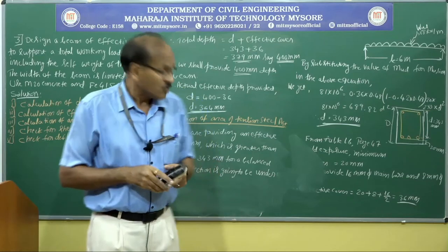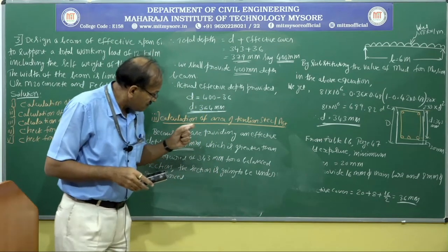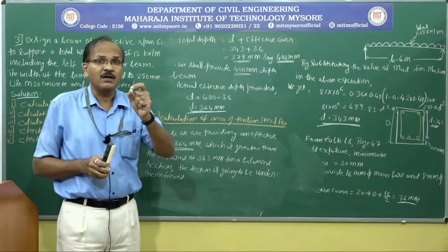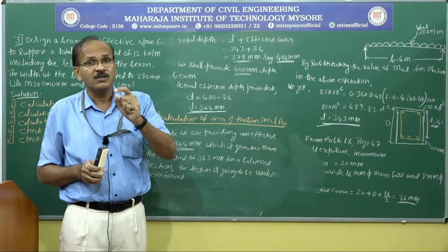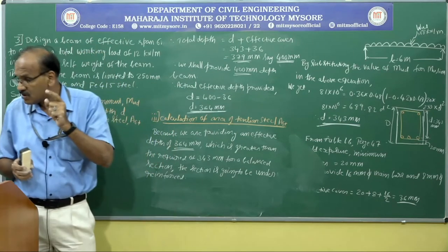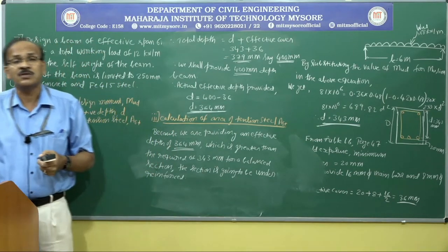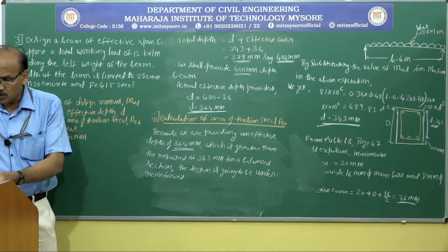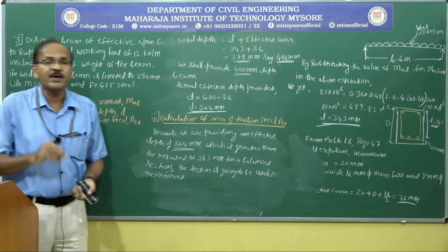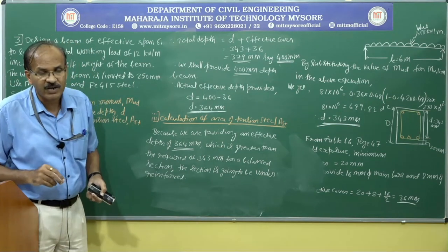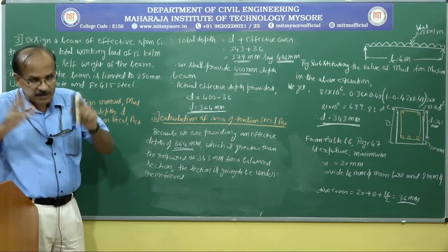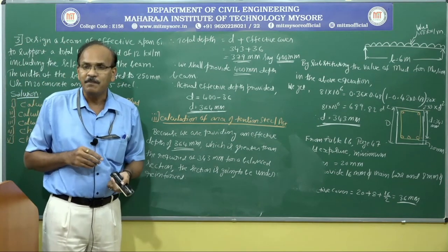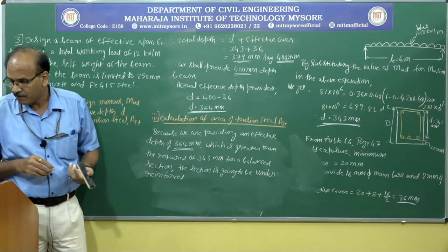Okay. So once it is under reinforced, to find out the area of steel for an under reinforced section, the formula we can make use of is on page number 96. You have the formula under G-1.1.b. So what is the formula we have? That is Mu equal to 0.87 Fy Ast multiplied by d times 1 minus Ast Fy divided by b d fck. Okay.